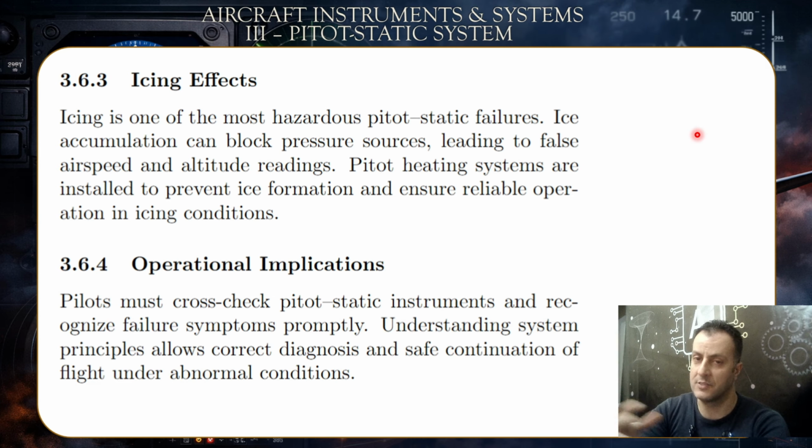Not only the instruments, by the way, it affects the entire airplane, especially by introducing drag on the wings, and it can lead to a stall by reducing the lift and increasing the drag, deteriorating the wing characteristics and converting laminar flow into turbulent flow. This will kill the lift force that is supposed to be pushing the plane upward and keeping it in the air. So, icing effects.